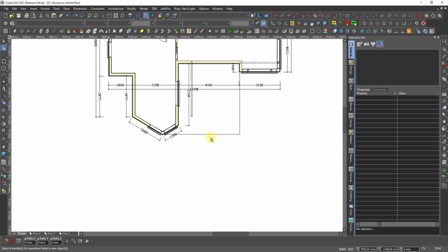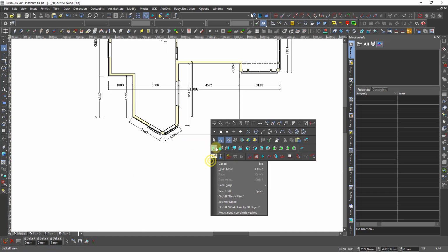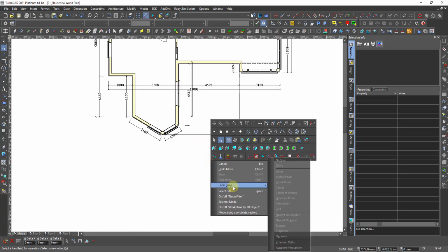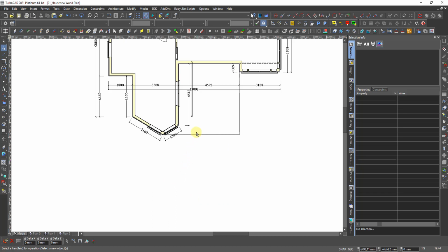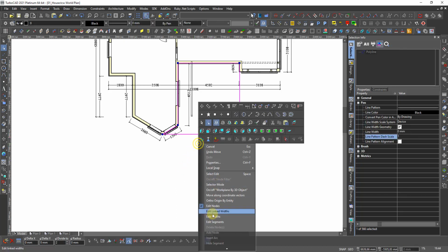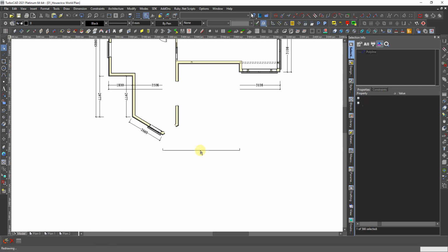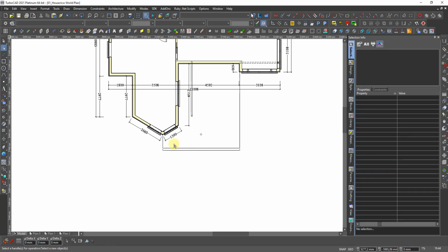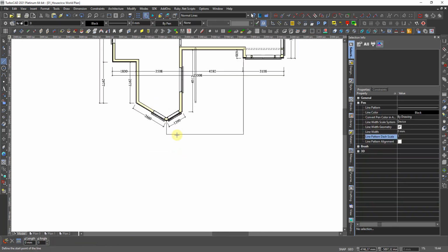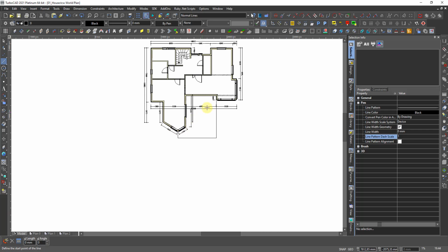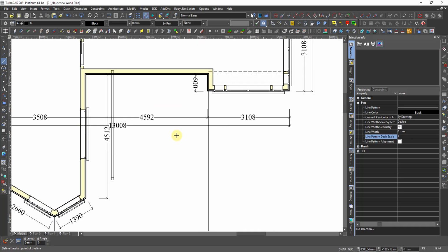And I want this 1 meter more out. So I go to, if I select it first, segment. I want this to go 1 meter in Y. Then it will be 0 and minus 1 to 1000. That's 1 meter. Then I finish this, and I have the terrace like I want it. It's supposed to be a terrace.